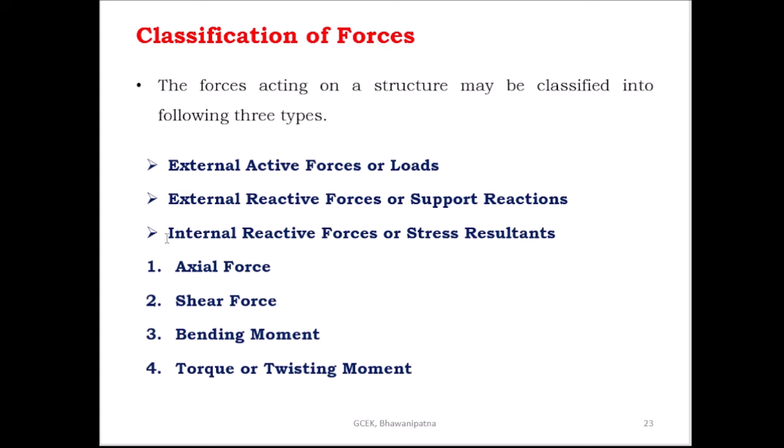The third type of force is internal reactive forces or stress resultants. This force is induced in the structural members as a consequence of the applied load. Every element of the structure is strained. This is the stress resultant. So this is axial force, shear force, bending moment, and torque or twisting moment. These are the forces which are developed in the members of skeletal structures.